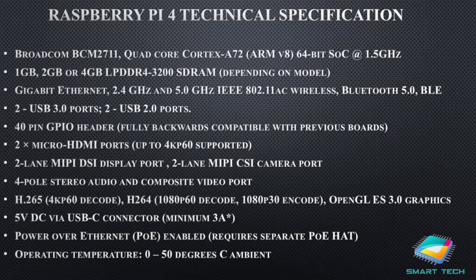It has 4 USB ports, USB 3.0 and USB 2.0 ports are available, and a 40 pin GPIO header which is fully compatible with backward boards. It has 2 micro HDMI ports, 2-lane MIPI DSI display ports, 4-pole stereo audio and composite video port.